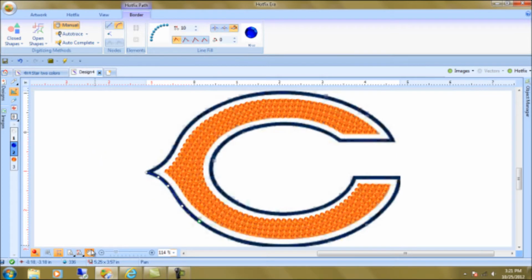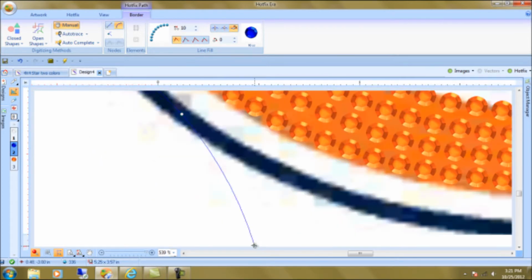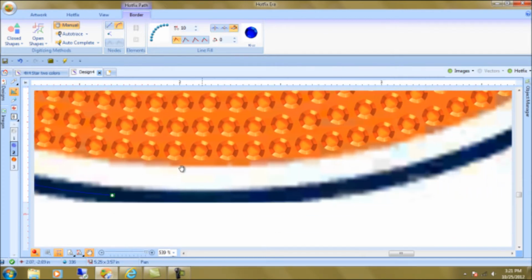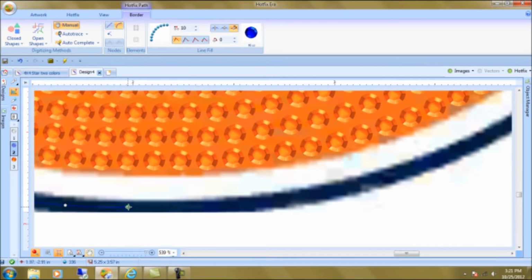Use my hand tool, so I don't have to keep zooming out like that, and zooming back in, and keep going. Using your hand tool, or it's better called panning tool, allows you to pan around the design. You can actually get it quicker. Being zoomed out too much oftentimes makes me target, move, and try to set that node where I want it to be, right in the middle, and sometimes it's not if I'm zoomed out, and then I have to hit backspace and redo it. So by staying zoomed in, I can target and move through my design much more rapidly.